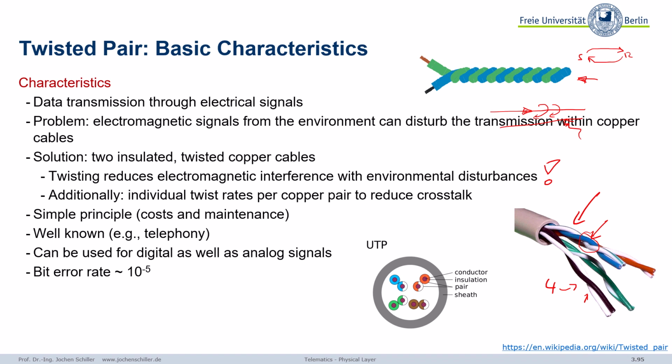One is the bending radius. So if you have such a cable, never bend it too much. There's a so-called bending radius you have to follow, for example, 15 centimeters or whatever bending radius. That means you have to follow this circle with a certain radius of, for example, 15 centimeters.